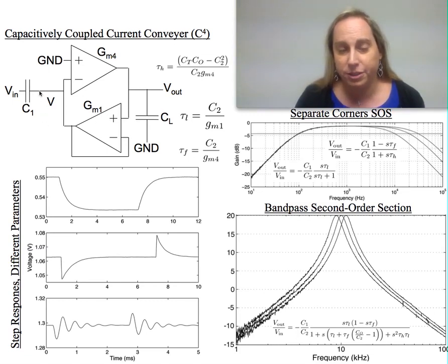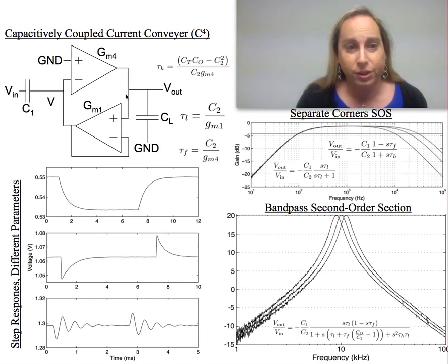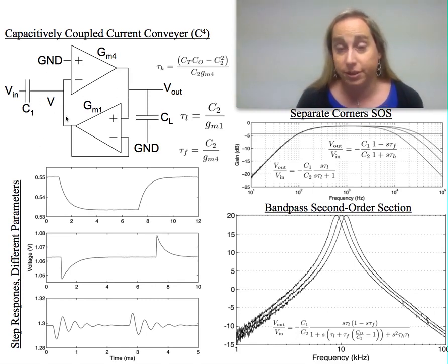There can of course be additional capacitance here, CW, down to ground or a fixed potential. There can also be a capacitance between the middle node, which was analogous to the floating gate node in some of those circuits, and the output voltage. That would typically be C2. Trying to keep this consistent with some of the other discussions, there are much longer papers that go through this in great detail, but to give a sense of what's possible, I wanted to walk through a few of these aspects.